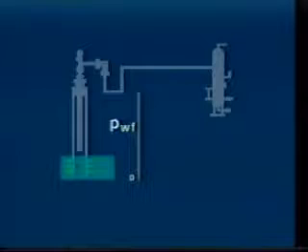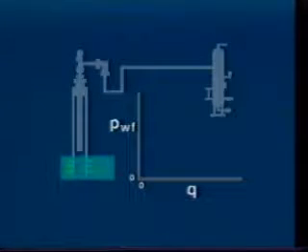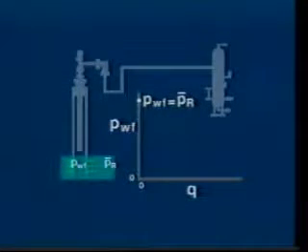For illustration purposes, we shall show a plot of pressure, P sub WF, versus flow rate, Q, with pressure on the vertical axis and flow rate on the horizontal. Before a well is opened to production, the pressure at the perforations, P sub WF, is equal to the average pressure in the reservoir, P sub R bar. The flow rate is 0. Because the vertical axis is the well bore pressure, we have a simple point on our graph.